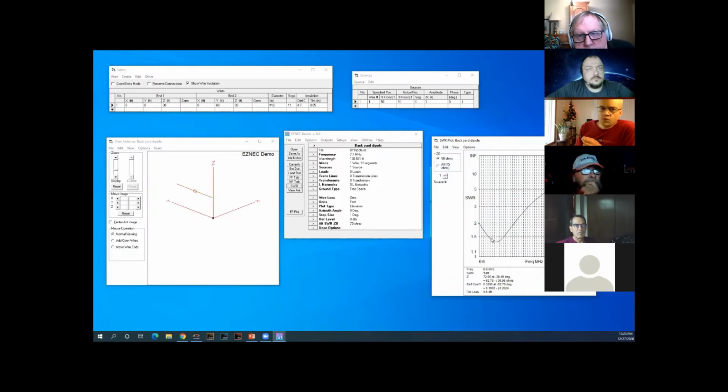And just anecdotally here, down in North Carolina, I had a dipole where the center was 30 feet away from a tree. And normally that would be a 33-foot leg on each half of my 40-meter dipole. I put it up with insulated wire, and the length turned out to be about 30 feet, and it fit perfectly. So sometimes that's very useful. You can actually go ahead and do it.